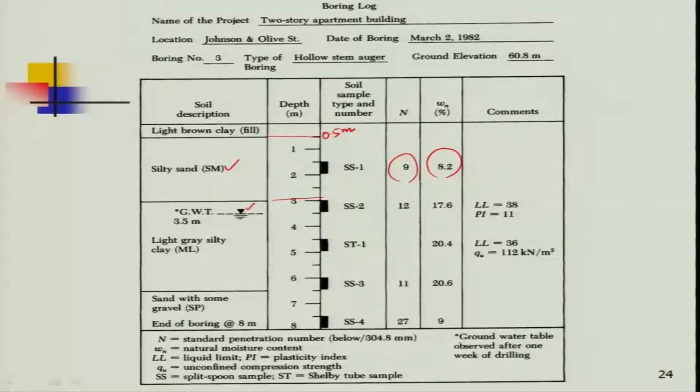Then you can mention the liquid limit and plastic limit. This is how the bore log data reads. This is only the information about boring, classification, SPT N and natural moisture content. If you have carried out any dynamic tests, such as seismic, downhole or crosshole, I have not gone into dynamic tests yet; I keep that for the lecture on foundation design, machine foundation, where I am clubbing it.